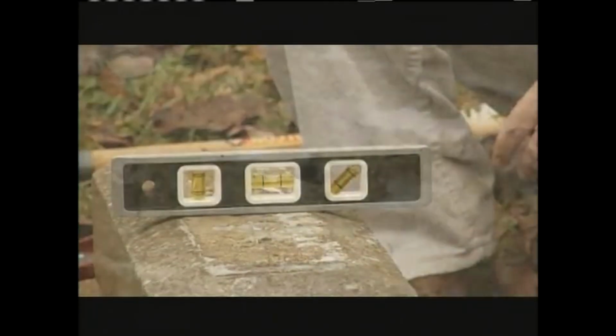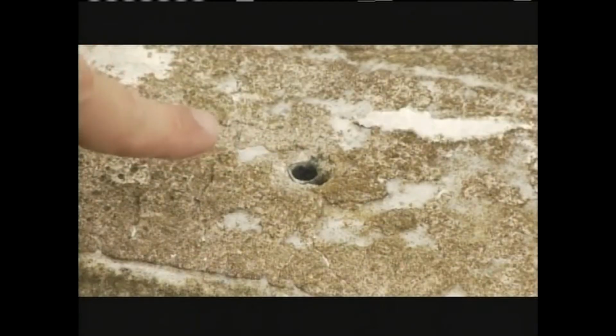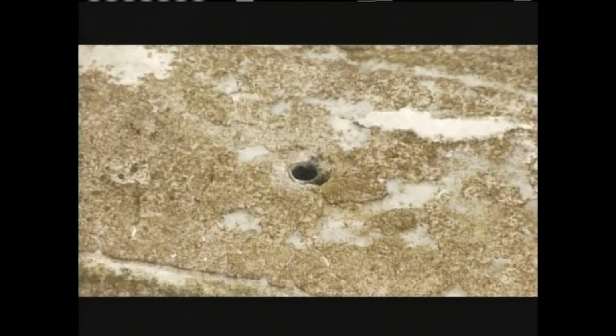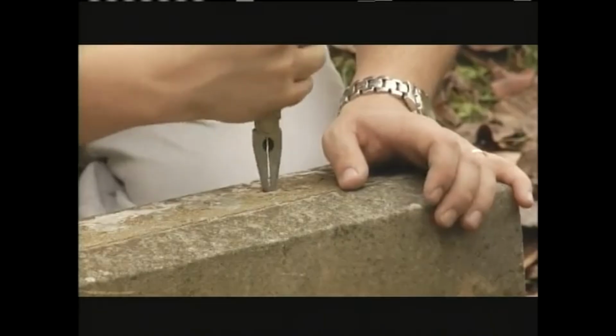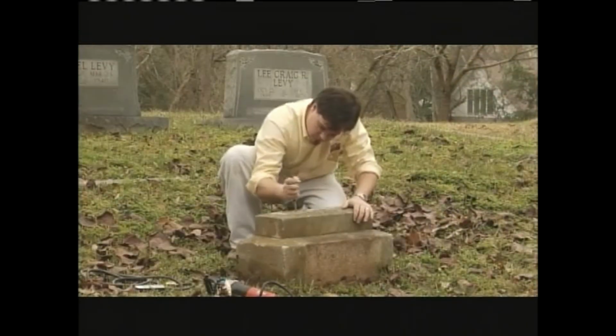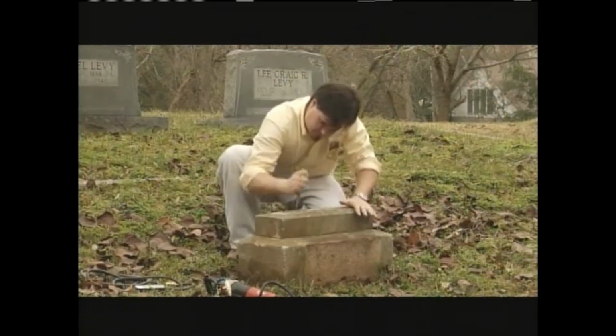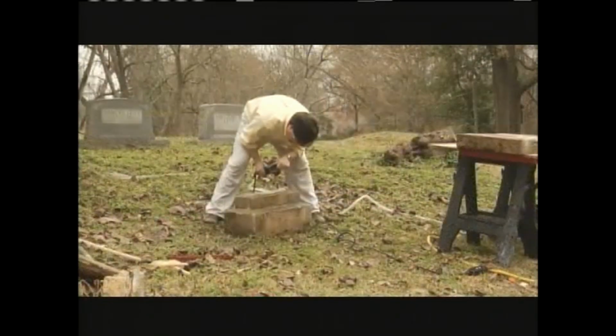Without a stable and plumb base, any repairs to be done to the stone will run the risk of failing in the future. We can see that this base once had two small bronze pipes inserted to try and stabilize the headstone. For whatever reason in the past, these pins have failed. Our next task is to remove these failed pins. Many times you can remove the old pins with a good pair of vice grip pliers. If this does not work, or the pins have severely corroded, as in the case with most iron pins, you will need to drill the pins out.